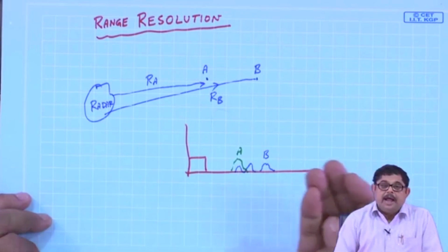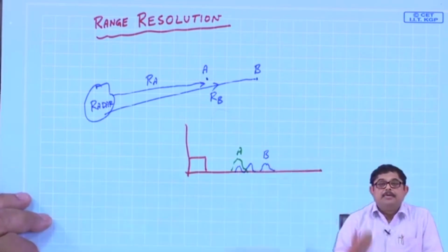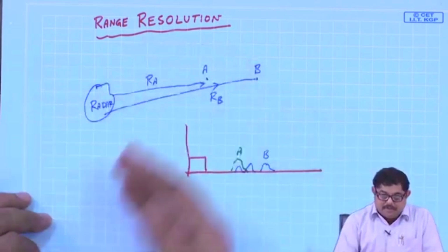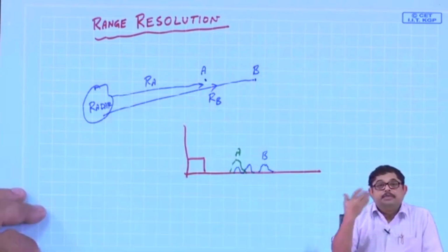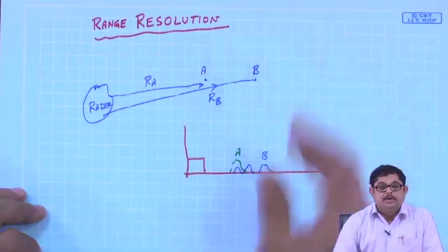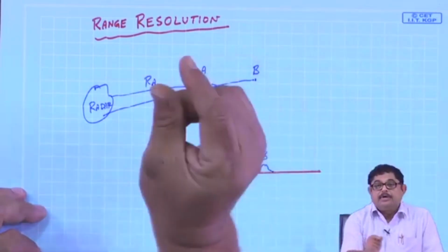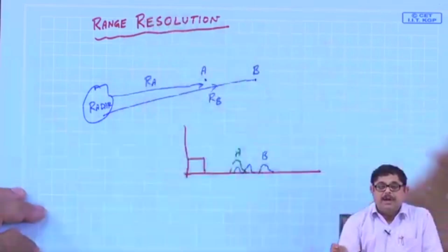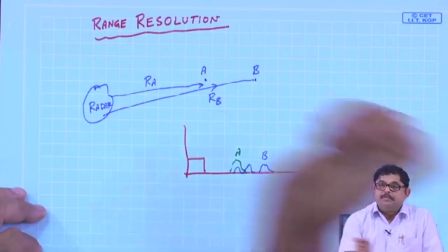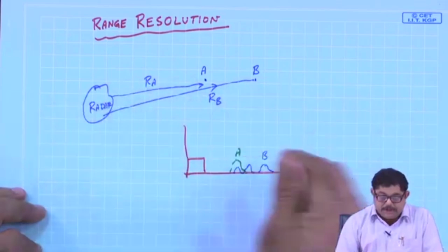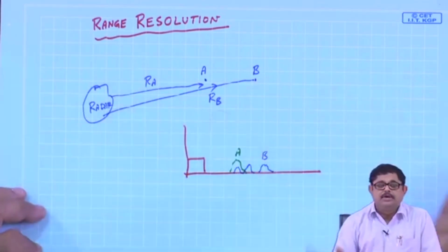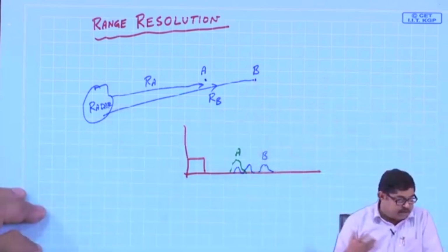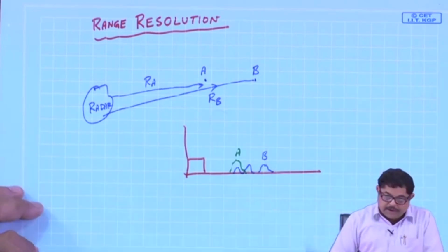So, you can make this resolution several orders of magnitude lower compared to this. Also, besides the range resolution, there is also a resolution in the angular direction, or in terms of range it is called cross range resolution. So, we will see there is a concept of down range resolution, cross range resolution, those will come later one by one. Now, we are not entering there.